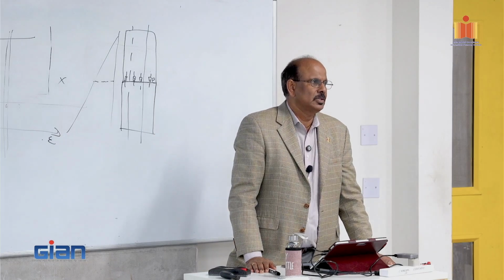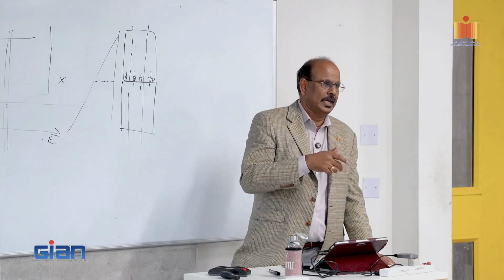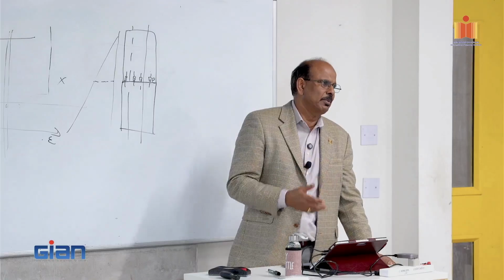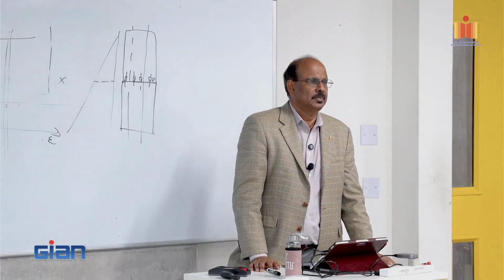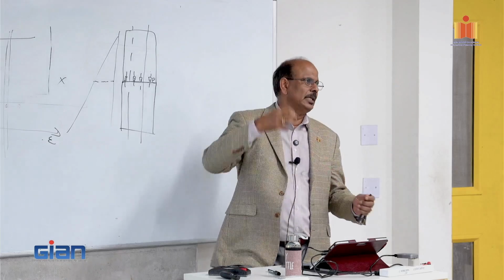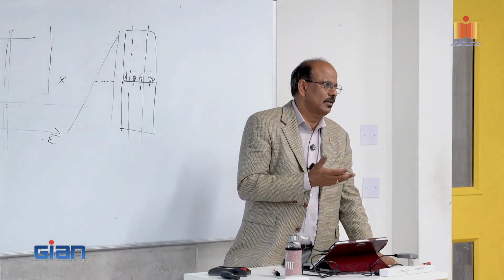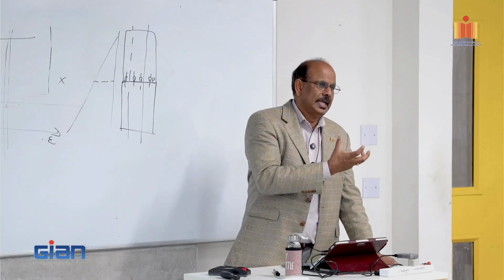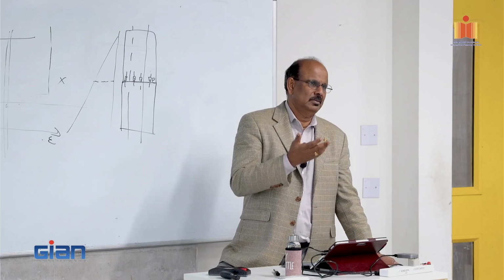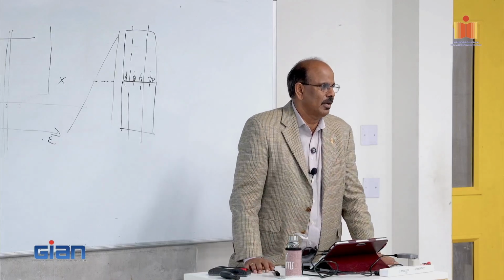In some of these tests, actually, we tried to remove the wedges, to see if we can remove them easily. They can be done fairly easily. They don't get jammed and things like that. They just pull back and then the wedges come out. They cannot reuse any of the wedges or the anchor head. They go through some localized damage, but you have to put in new ones; you're not replacing the entire building, right? So the cost is nothing.